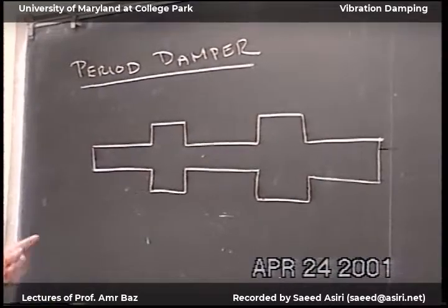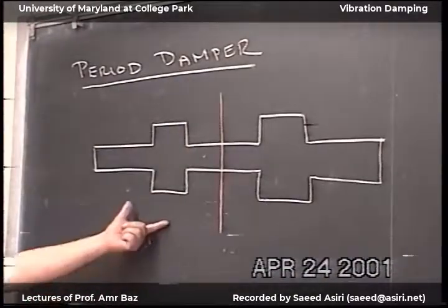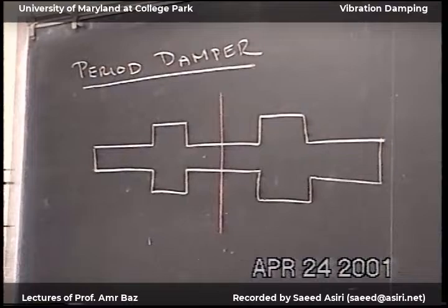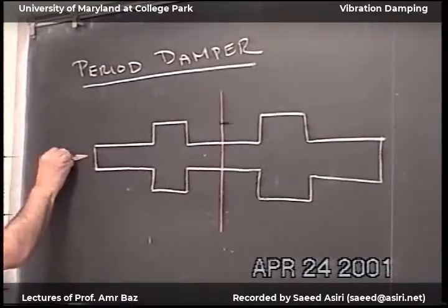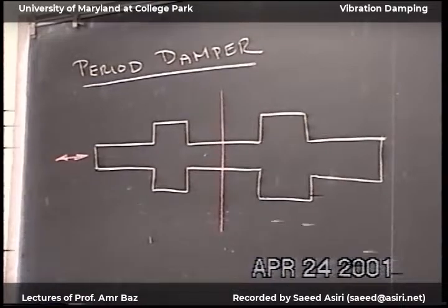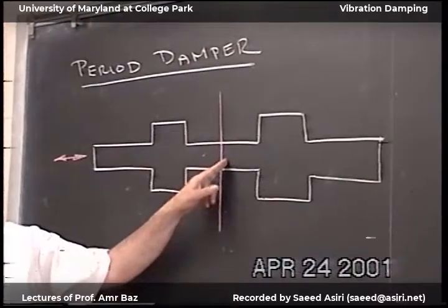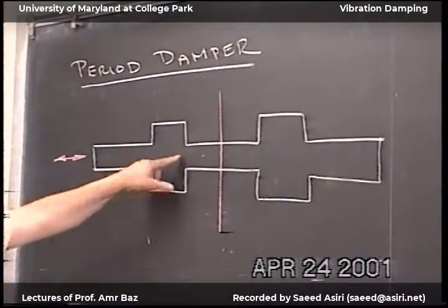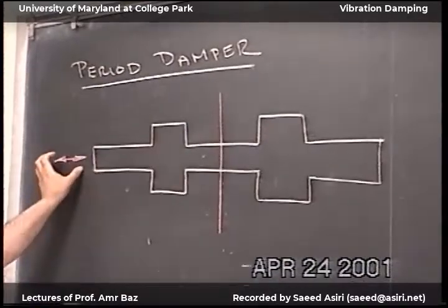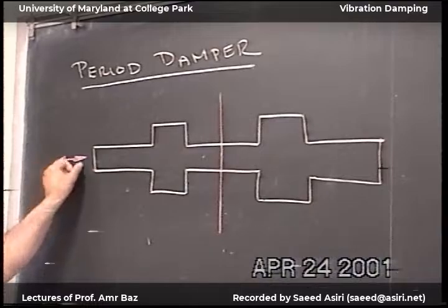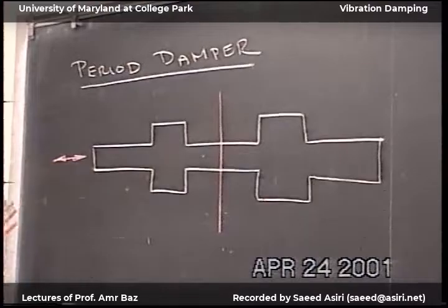And we know that this works because if you look at half of this, this looks like the car muffler. The car muffler, you come here from this end, you give high pressure fluctuation in the engine. And what comes out of the tailpipe is low pressure fluctuation wave. And in between, you use this change in geometry to attenuate the vibration or the acoustics from one place to another place. Now if I make many of these, I can have many mufflers.